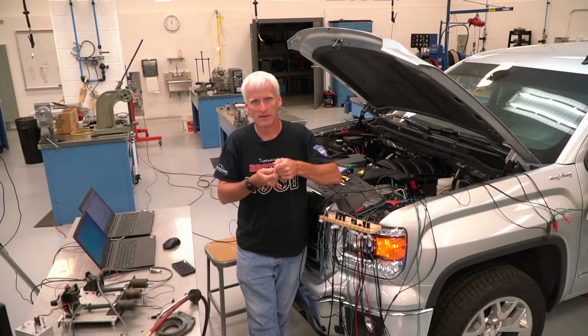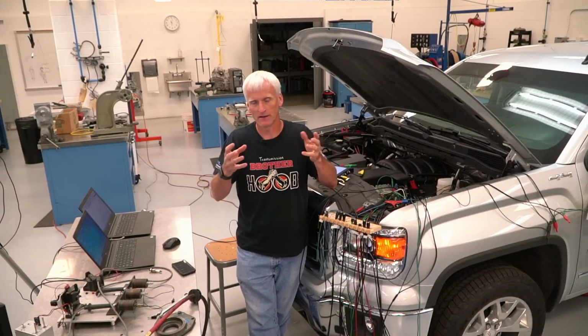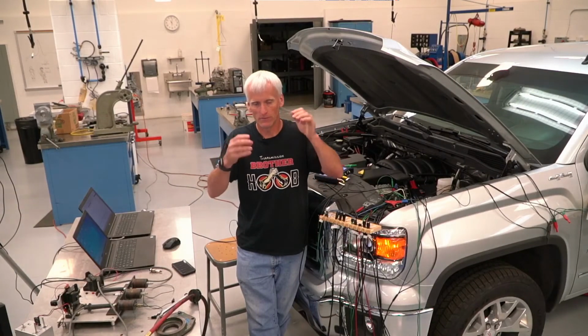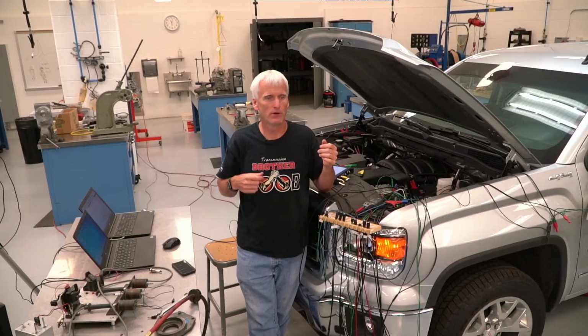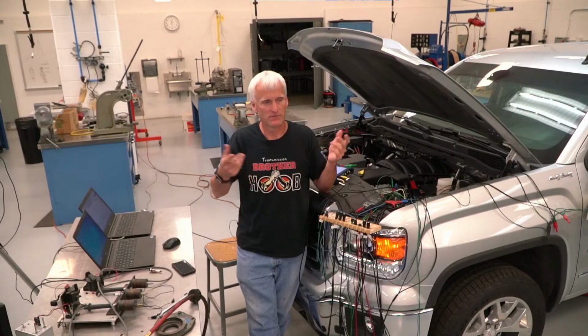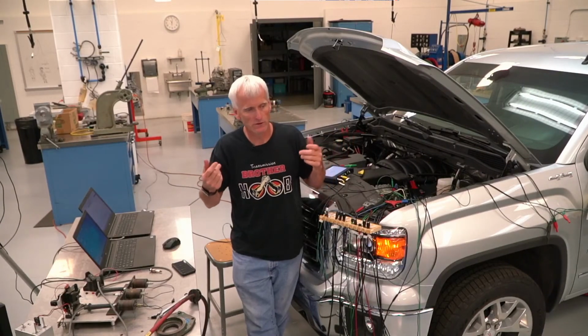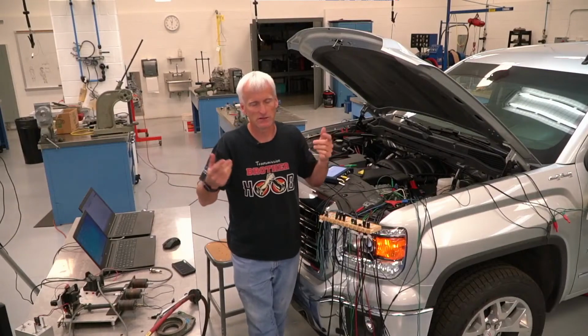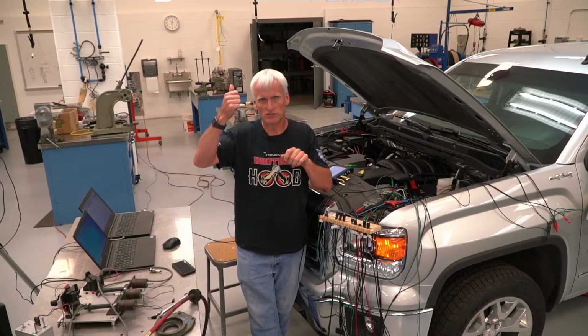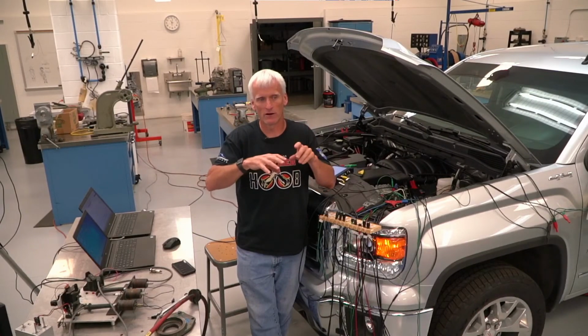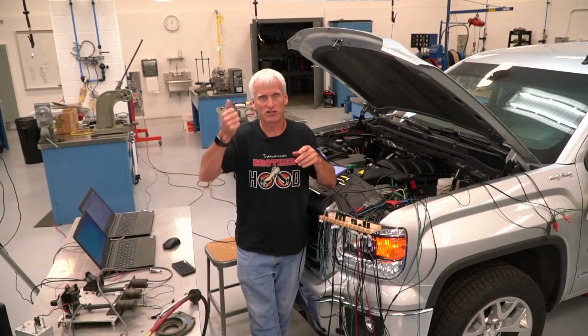Then I mixed argon in there. So I had just argon in the tube. O2 sensors were still putting out like 20, 30 millivolts. Then I put oxygen in there. Didn't change it, which doesn't surprise me at all, because with oxygen in there, you'd expect it to be low anyway. So then I took a little bit of propane and blipped a little bit of propane in there and it shot up. So it was with nitrogen or argon and propane, it shot up.